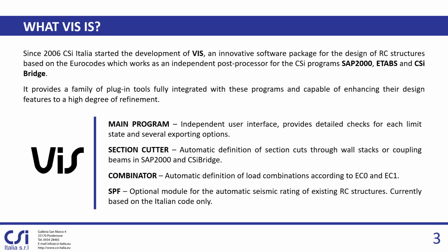And the last one is SPF, which stands for Seismic Performance Finder, which is an optional module for the automatic seismic rating of existing reinforced concrete structures. SPF basically works by running a set of incremental dynamic analyses varying the seismic intensity with the purpose of finding the critical level of the seismic force that the structure is able to withstand. Currently, it is based on the Italian code only, but of course we plan to make it compatible with the Eurocode as well.